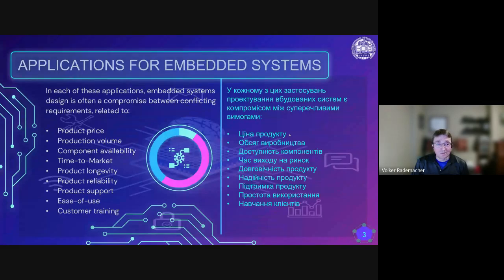The problem was that you could never quite exactly hit the threshold at which the hardware comparators for the outside LEDs were running. So in testing, there was always a situation where the test personnel was able to indicate a certain amount of ground fault, and the software would show a different amount because of the tolerances in components. So sometimes the pressure of trying to save components will create problems for the developer that need to be addressed right away.